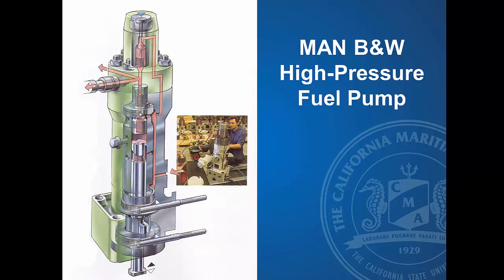While you're injecting air into the cylinder, that puncture valve is activated so that you have no fuel delivery until the engine rotation comes up. Then that signal goes away, the puncture valve closes, fuel injection starts, and immediately afterwards the start air is secured.